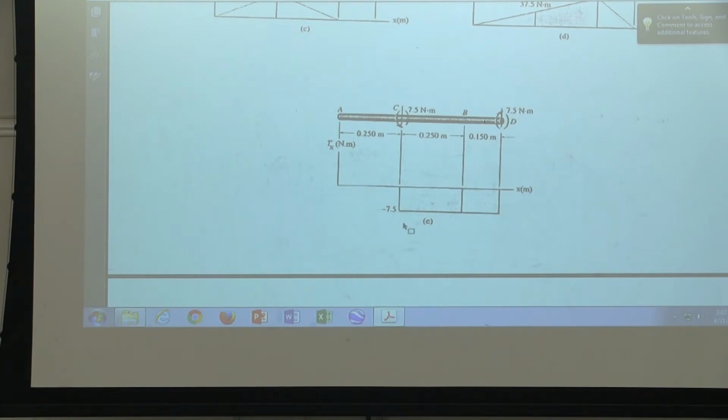As I said, you can consider here minus or plus, depending on whether you are considering action or reaction, left-hand side or right-hand side. Everybody understand what I'm saying? If you consider this as positive when you cut it here, that reaction would have been negative, yes or no? So they draw this as negative.